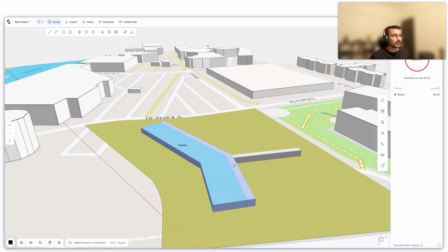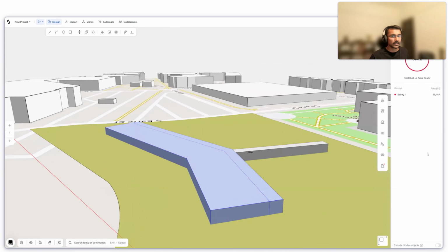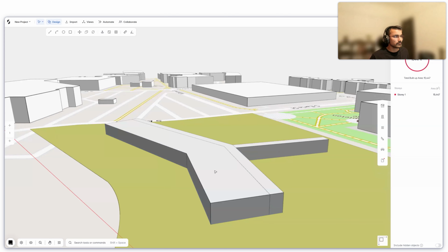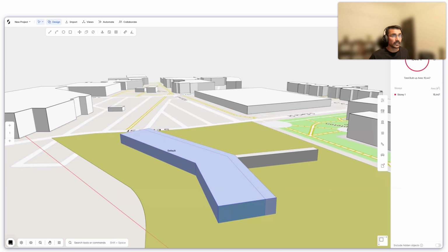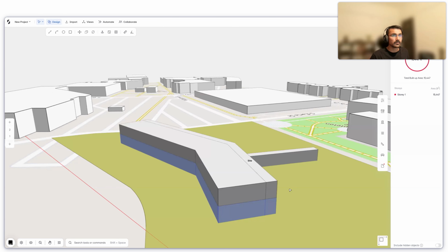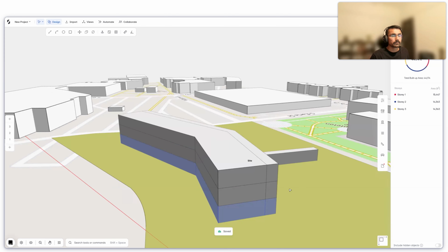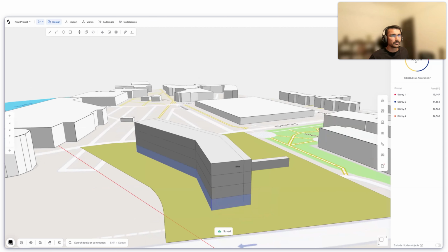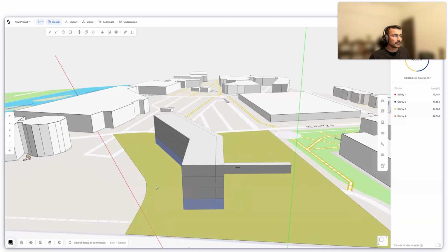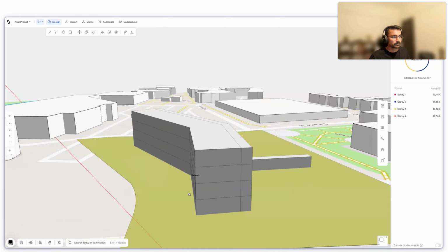And what I'll do next is to achieve that area of 65,000. I'm just going to copy these up. Before doing that, let me just quickly change the story height from the default 10 feet to 15 feet. Cool. Now I take these and let me copy them up. Keep your eyes on the area charts here as you see them change. And once more. Okay, so that's reasonable. We wanted 65, but we are achieving 58,000 with this. So I think we can plan this wing to be 4 stories tall.